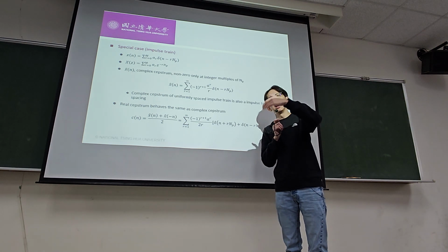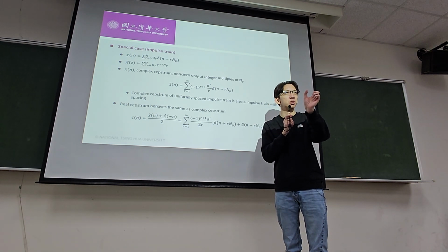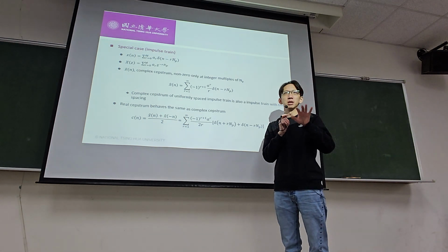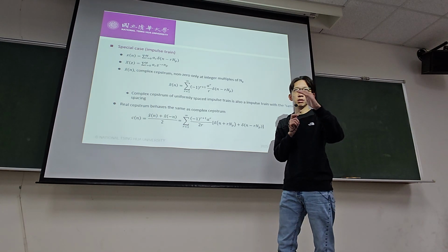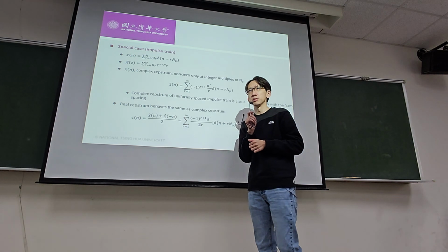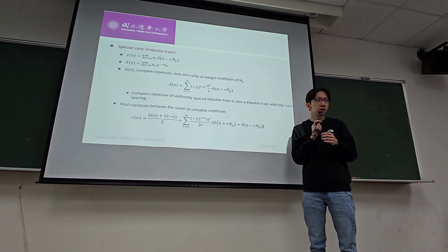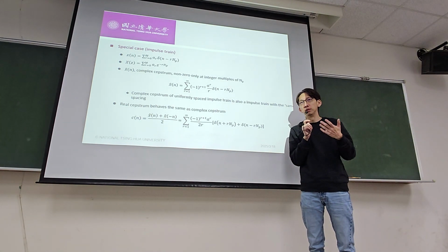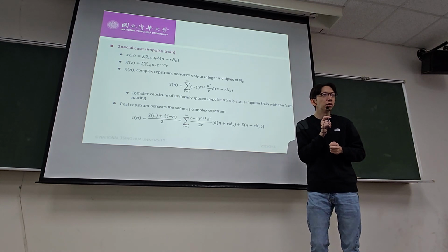So you're effectively looking back into the time domain, but not quite, because you have a log operation within it. But that intuition should tell you the original periodicity will be preserved. Whatever periodicity is there in the time domain, the complex cepstrum will have the same periodicity, and that tells us there can be algorithms designed to detect pitch from the cepstrum, because the cepstrum will have the same periodicity as the original time domain signal.